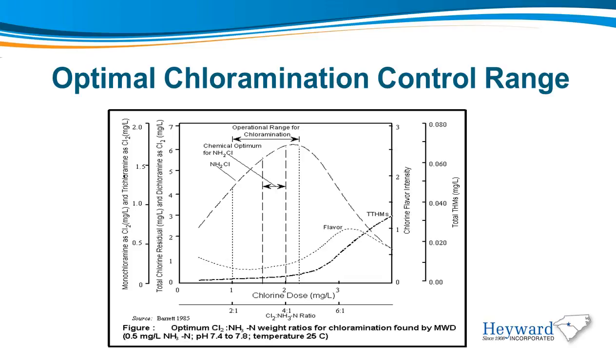These forms are also more reactive than monochloramine and will increase the disinfection byproducts, as indicated in the total trihalomethane line on the graph. To avoid this, the chlorine could be dosed at a lower ratio. Below 4:1, however, free ammonia in reservoirs and distribution may promote the formation of nitrifying bacteria. Once nitrification begins, the available chlorine residual can plummet as the disinfection demand increases.